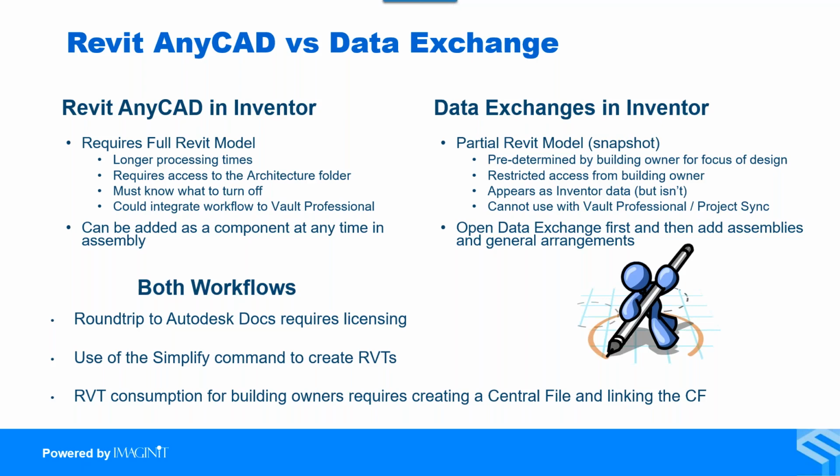And the way that you consume that in Inventor is you can consume it as a component anytime you want in your general arrangement. So I could be working on my equipment and then bring the Revit model in at any time, just placing it like a normal component.